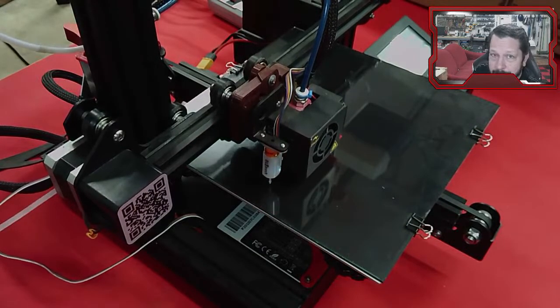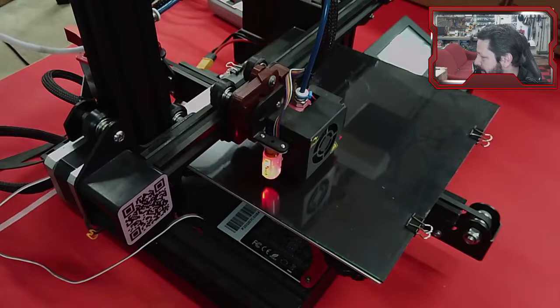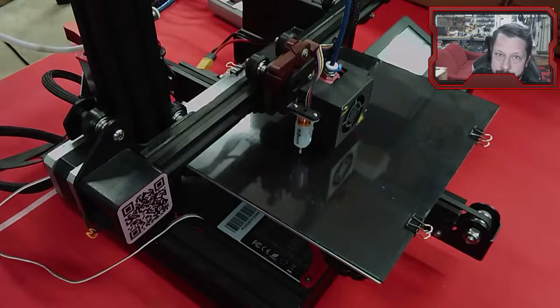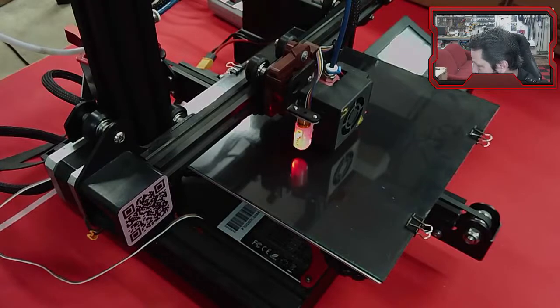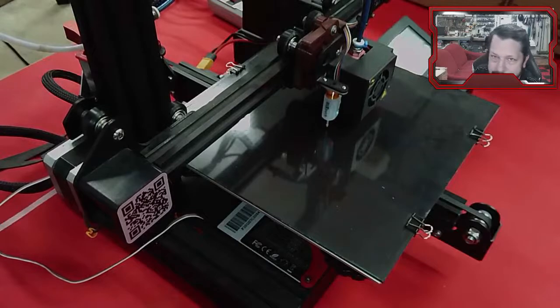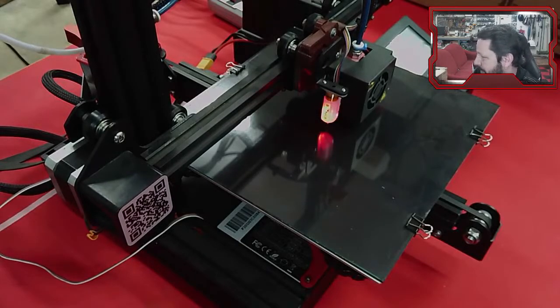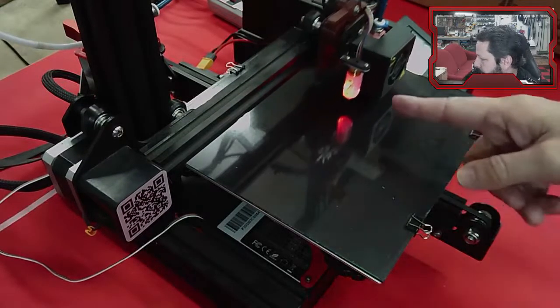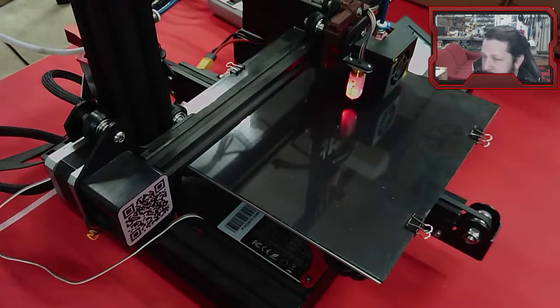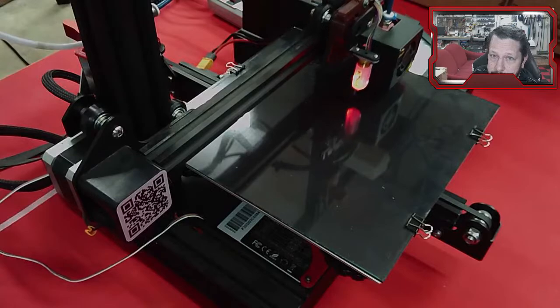So it will start out one shape, and then as it heats up, it will enter a new state of deformation. And that's hard to deal with because it doesn't always deform exactly the same every time. I mean, it's close, but that's why on a larger bed, these automatic bed leveling sensors are pretty valuable.